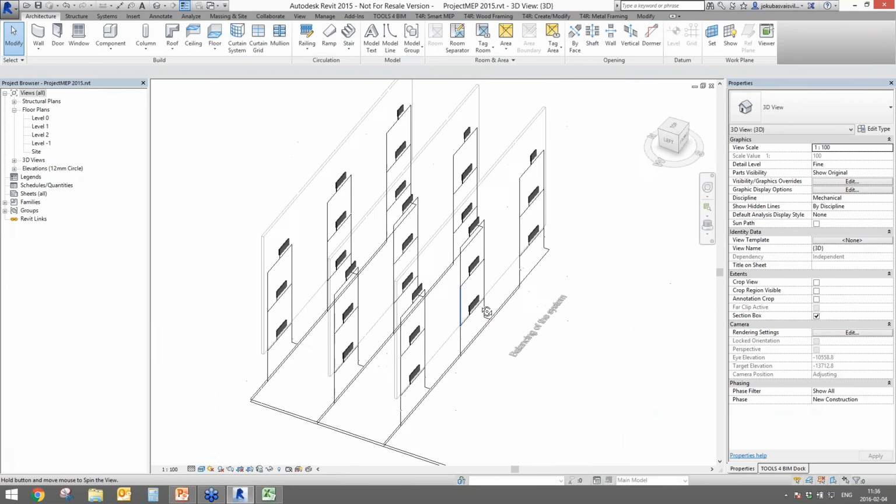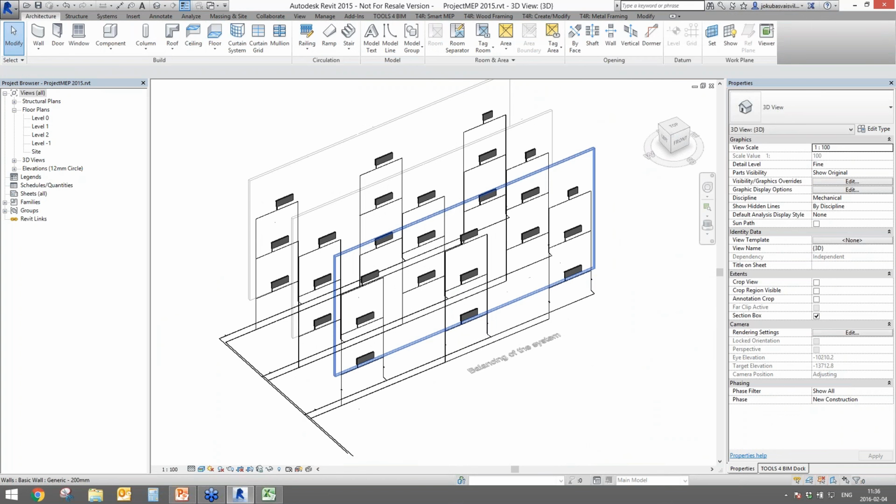It is working pretty good, and it is using the iteration method to make the flows equal to all the mechanical equipment. And it is trying to write some values in the key that will close or open your balancing valves, and in such a workflow it is trying to make the flows equal.